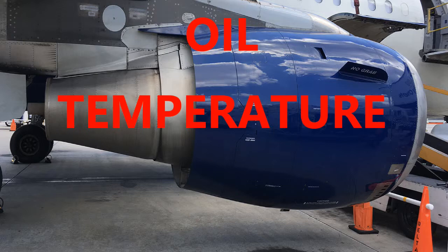Now, we also have the engine oil temperature. That was for engine condition, but we also have the engine oil temperature sensor for the IDG cooling system control. This particular sensor is located above the oil tank and on the oil supply tube to the forward bearing sump, and that runs at about the 9 o'clock position. So this is the difference: this is the engine oil temperature sensor for the IDG cooling system control.